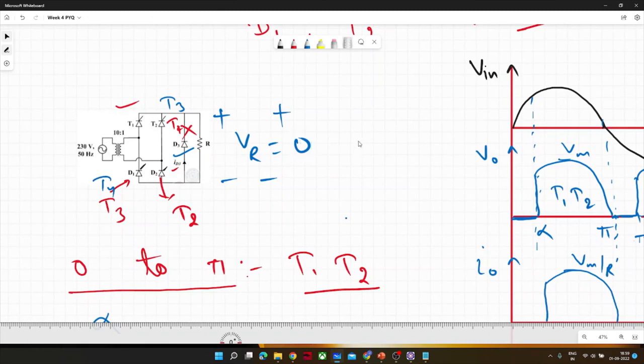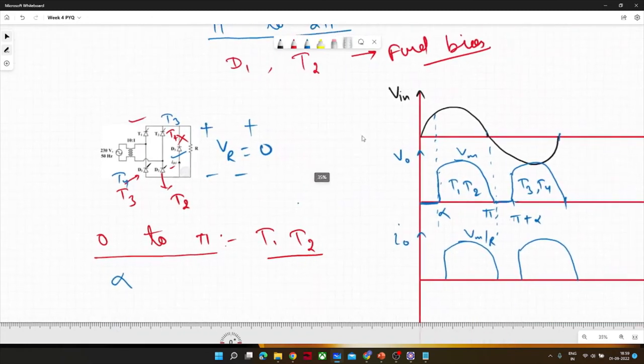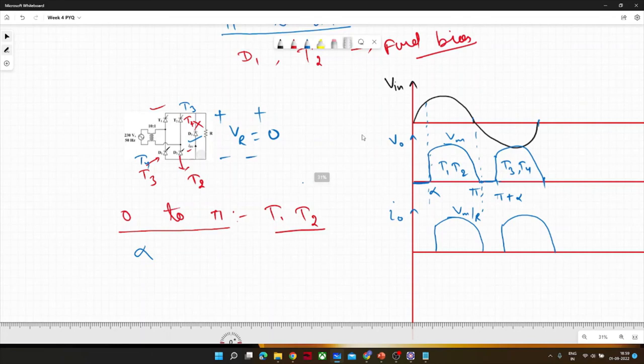Thanks, Anubhav. So I hope you got this point. This was the basics behind this. If it is a resistive load, it will not conduct beyond pi. And in a semi-converter also, after pi, conduction is not possible, because the voltage waveform would be the same irrespective of any load. Why? Because after pi, if any energy element is there, it would freewheel through this diode. If freewheeling is going on, voltage is zero, but of course some current would be there.